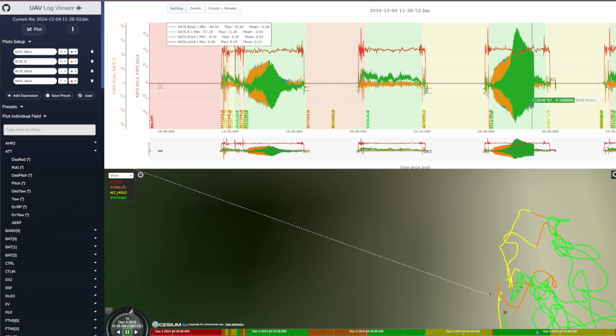Now the recovery roll angle feeds that chirp in directly into the attitude target and turns off the command model, which means that the high frequency response is greater. So it's good if you actually want to get some more power in the high frequency response. But you can see here that the rate output's actually increased above the throttle level, and this will mean we'll start to get saturation. And you can actually see here that during this system ID I had to reduce the throttle slightly to stop it climbing. And so this isn't what you want to see.